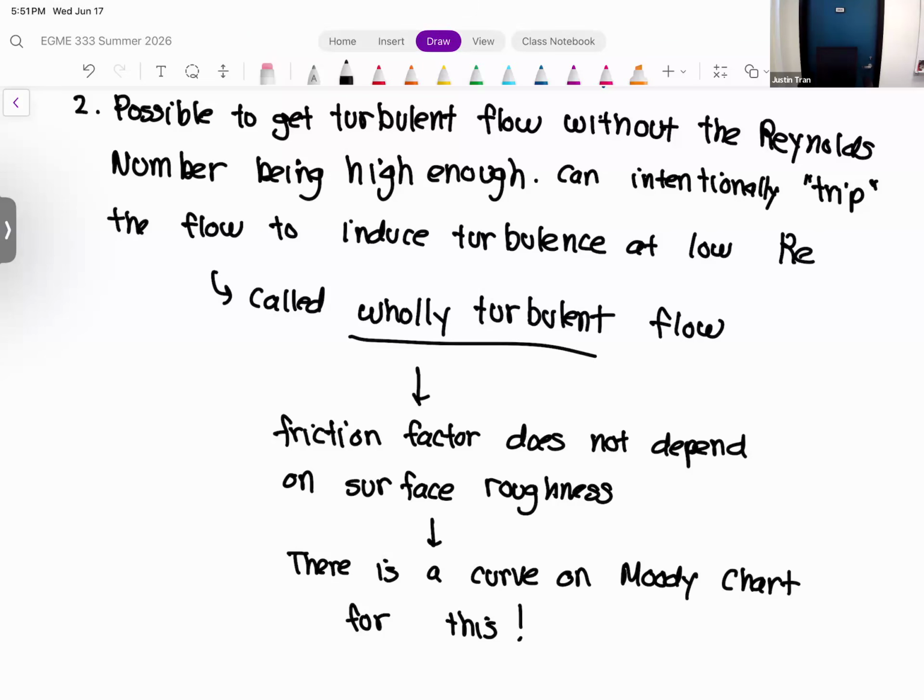So that's one way to manipulate it, because if you can manipulate the flow to be turbulent, then you actually have better control. It's easier to manipulate turbulence than it is to manipulate laminar flow. It is possible to get laminar flow, but you have to have a flow straightener, which people do as well. I haven't heard of people using dimples on a manifold on a car, but I'm assuming they're manipulating the turbulence to have a certain Reynolds number, a certain value, just so that they can design it.